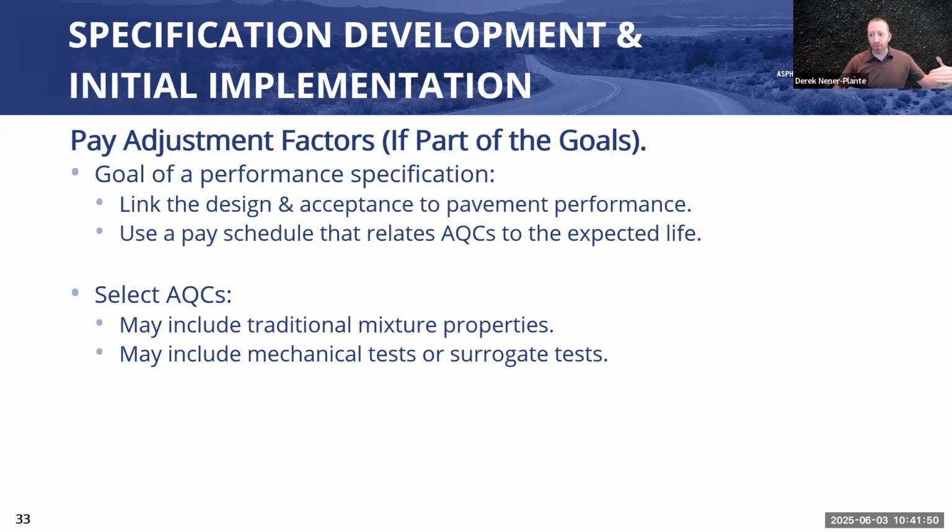We do that today with what we have. And what we're hoping is that balanced mix design, these mechanical tests and their properties, are an improvement upon what we have. But we do have to deal with the variability, the added testing time, all those things. It's not just going to be cut and dry, just sub them in. So developing that needs to be rational. Again, having validation efforts would be very useful, because then that can be defended.